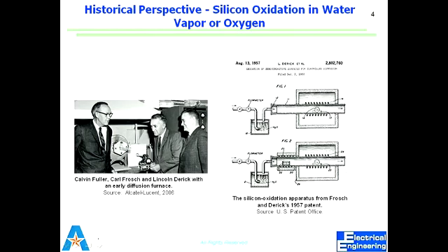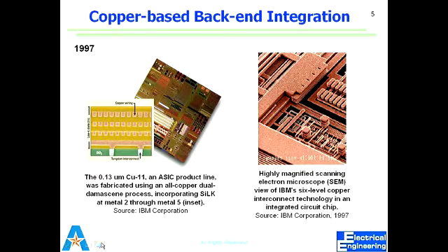These are heating coils. We pump in oxygen, which may be with water vapor or maybe just with nitrogen, and we let the reaction happen for a certain time. After that time, we take it out and we know we got the desired thickness of oxide grown on silicon. And then we put copper as well.